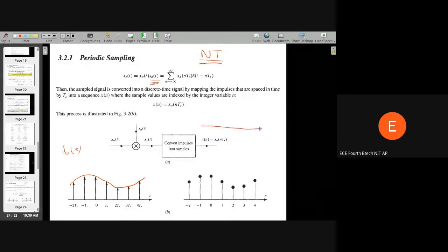This s(t) is nothing but unit impulse functions, a periodic train of impulses, and they are separated by a distance Ts. So this s(t) is represented like this, summation over n of delta(t minus nTs). If you multiply, then you will get this.